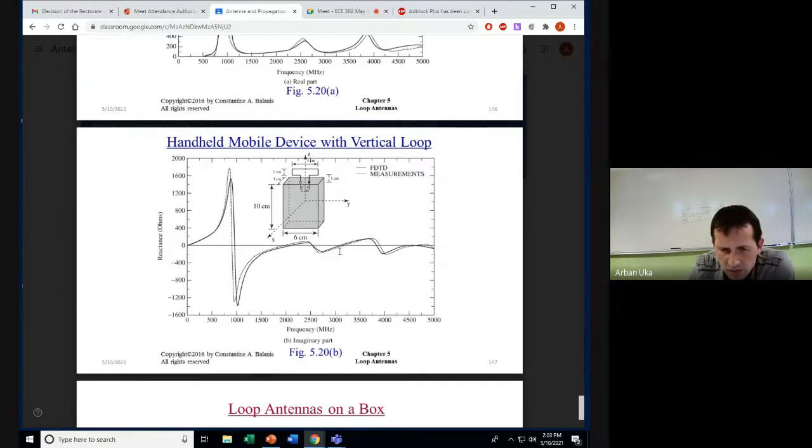Now this 900 megahertz, which could start as low as 750 to 900 megahertz, this is in fact the old communication frequency which has been used for cell phones in the United States and Europe. I always mix those. I think Europe used to use 800 megahertz and the US was 900, so that was the first. The second generation of cell phones immediately jumped for both continents to 1800, so it was twice the American frequency. So it was easier to buy cell phones in the US and use them in Europe and vice versa. So this was solved.